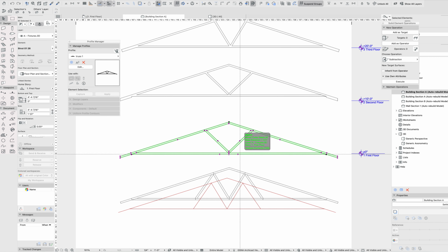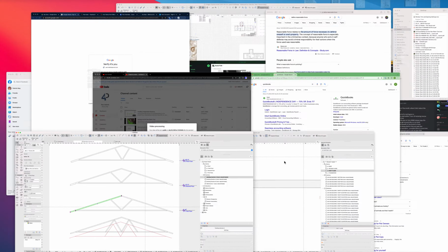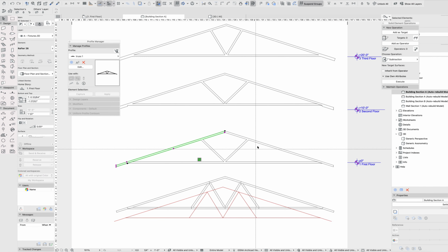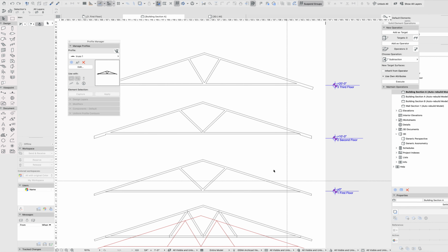Whether you're doing a stick built or a truss package, this can be really tedious and fussy to get this modeled out with these elements, because you don't have the edit functions. You can't extend, split, or even edit the truss as a whole. You have to edit each individual subpart of that truss. So this is probably one of the more tedious options.